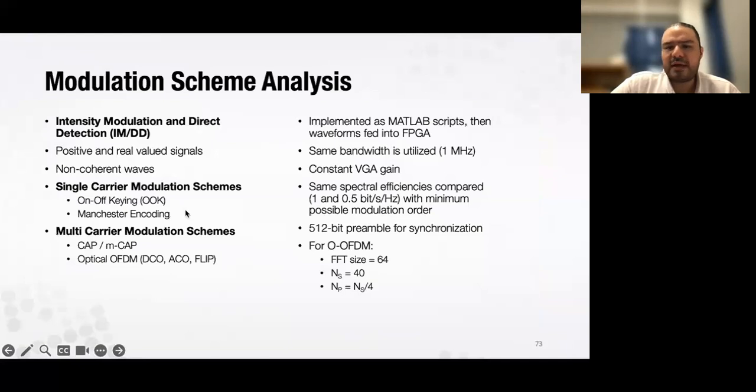to understand which modulation scheme works better, and then we did a study comparing different communication modules. To give you a sense, optical waves cannot send QAM because these are non-coherent signals. They work on intensity modulation or some adapted orthogonal frequency division multiplexing communication protocol. So it's a little different from RF. Again, it's quite unique in that sense, having primarily non-coherent waves that need special receiver and transmission schemes.